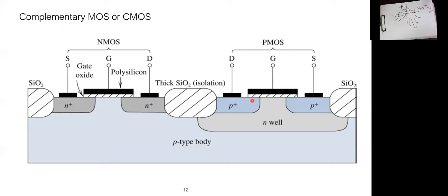In your next semester, in your VLSI course, you are going to build all your digital circuits based on these two MOSFETs, the N-channel MOSFET and the P-channel MOSFET. And you are going to combine them together in the same circuit under the technology of CMOS, or the complementary metal oxide semiconductor technology, which is the most famous technology in digital IC design theory. This is the termination of part number 1 in lecture number 4, dealing with MOSFETs.